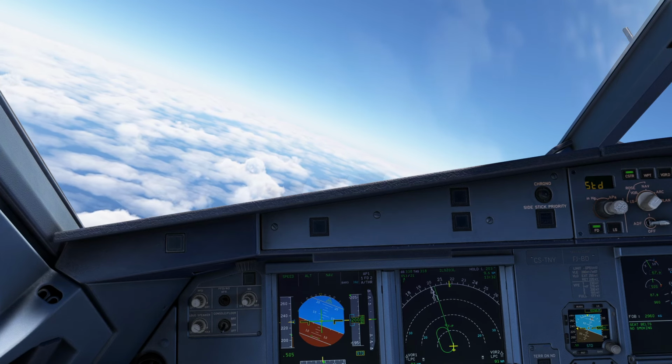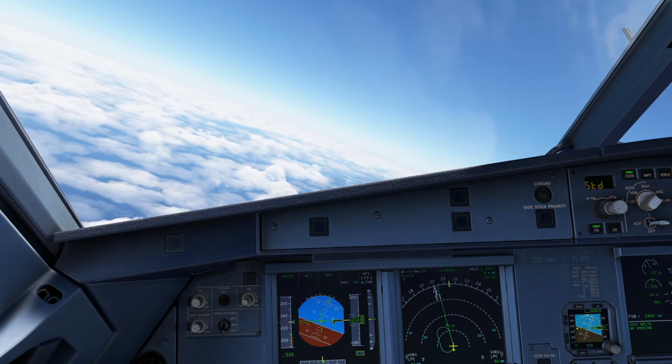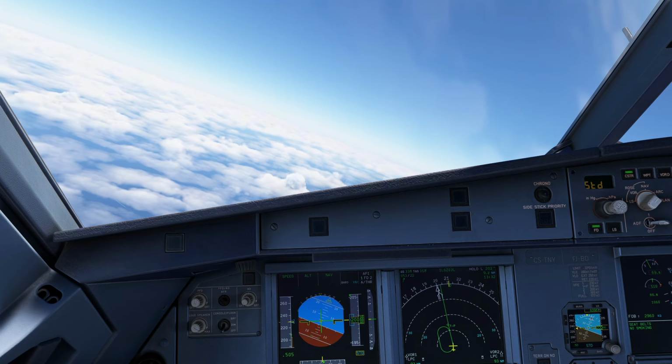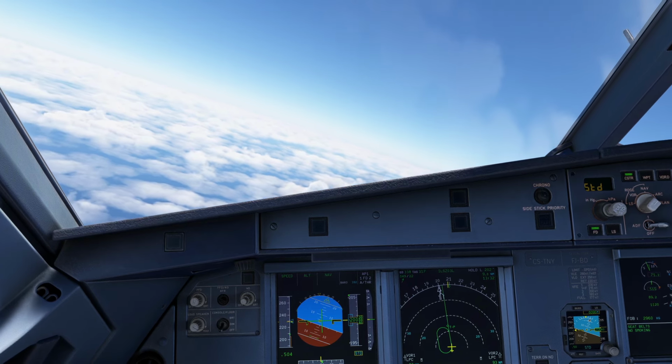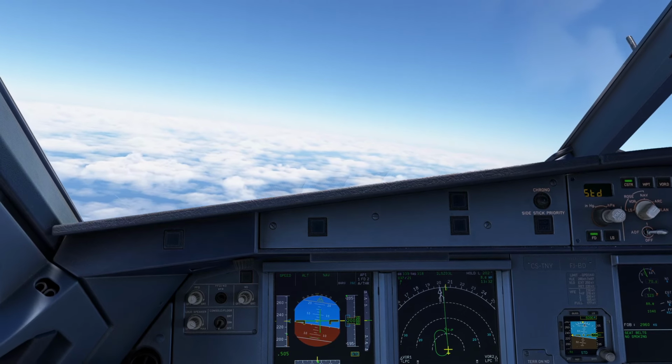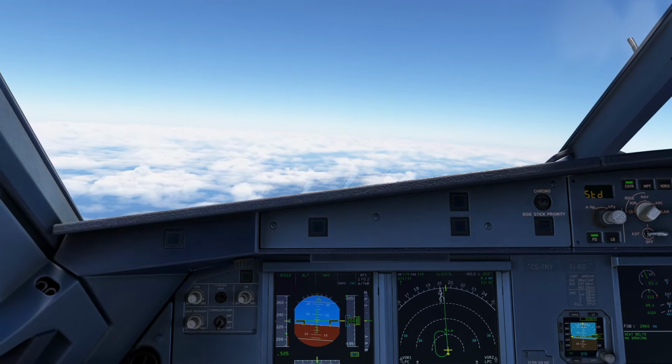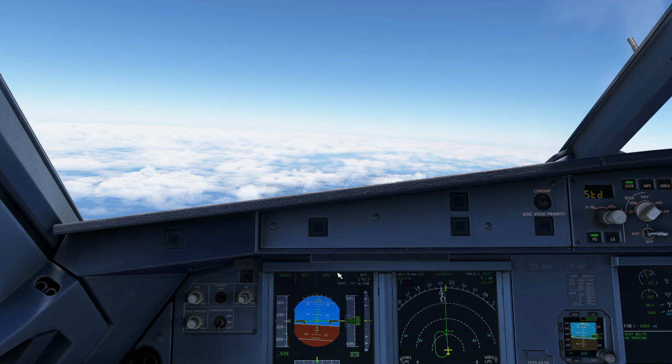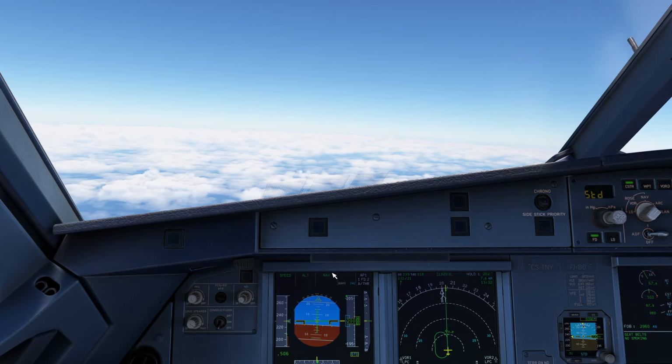At this stage, you got and understood the meaning of final descent point, which is frequently talked about in Airbus publications. When in nav mode, as right now, on the FMA you see the nav in green, with managed speed.